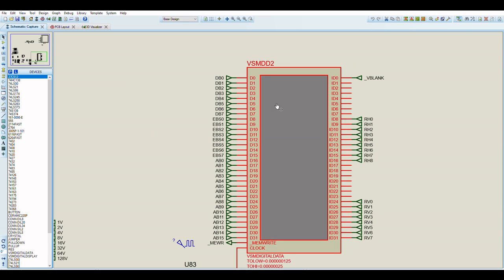This is actually not part of the standard Proteus simulation suite. It's actually an additional virtual device that I created because I wanted to make it easier for me to generate debug patterns to feed into the whole simulation, but I also wanted the ability to record. So this actually allows me to record or to play back, and this one plays back information from the testdata.txt file. It allows me to define a text-based format.